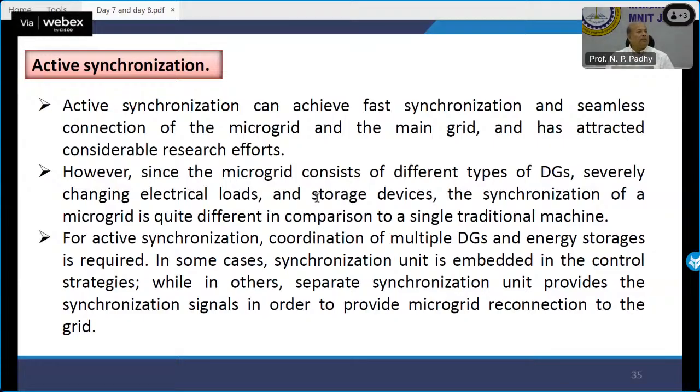Let's say you connected a microgrid at 11 kV. When you disconnect it, you will not be experiencing 11 kV. Maybe 10.5, 10.7. So when you go back to the grid, you have to make sure that 11 kV is available to you within the microgrid itself. That is important. You have to go to that point and then switch it on. Is it okay? Good, good.